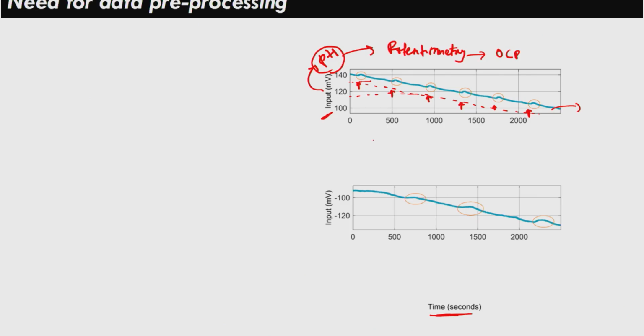This is data from one experiment, let us say experiment 1, and this is the data from another experiment, experiment 2. In experiment 2, the bumps in relation to the injection are much smaller and they are not visible. So, this tells us that we have to have some sort of processing method that can remove this drift and clean up the signal, so that the device can automatically and correctly estimate the analyte level, in this case pH.